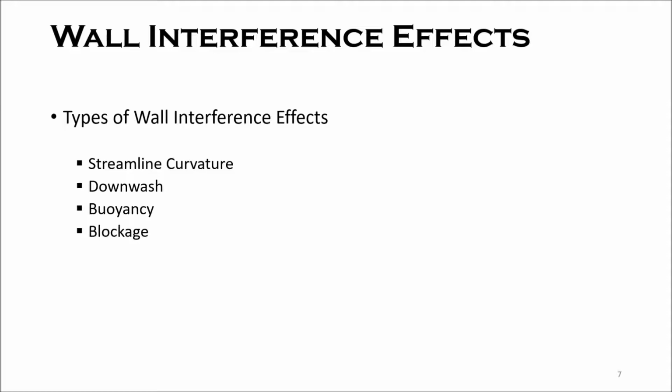Streamline curvature and downwash effects occur due to the characteristics of lifting bodies. Since the quadcopter being tested is a bluff body, only buoyancy and blockage effects are considered, which I will discuss in the next slides.